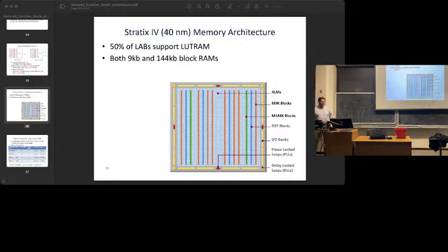And even if you had a lot of logical RAMs that fit very well to this 9 kilobit RAM, you might find, well, I've now used them all, right? And I'd have to buy a bigger chip. But maybe some of my logical RAMs are not bad in LUT RAM. Maybe they're not the best, but I've still got some logic left, so let's do that. Does that make sense? So there's kind of two pieces of the decision.